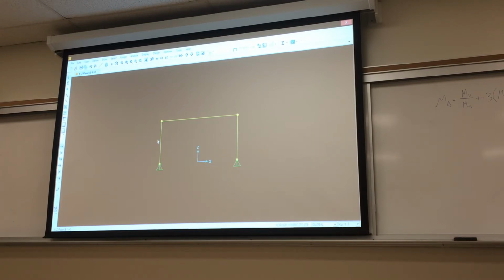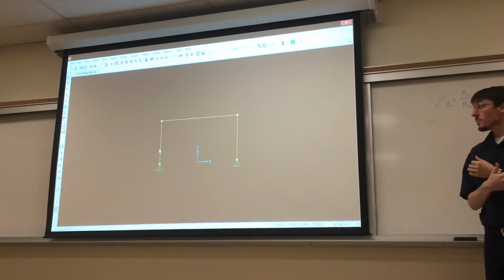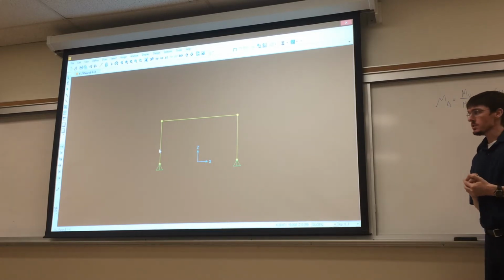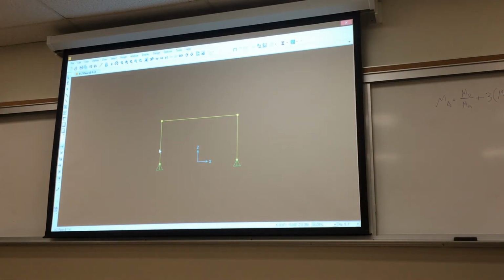So when I said finite element packages solve things by displacements, you basically define in your model what individual joints can do in terms of their displacement behavior. So for our structure, we're interested in just this two-dimensional analysis. So I'm interested in rotations along the y-axis, displacements potentially in z, and displacements potentially in x.